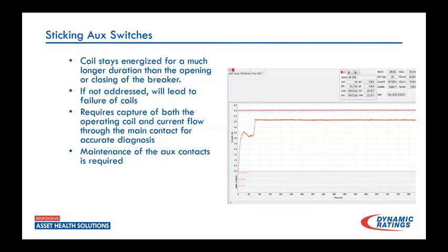And again, with more operations, you'll see this start to change. It may get better apparently after you operate a few times, but if it's really something you have to go in and do some maintenance on this, because the coils are not designed for this sustained current for this amount of time. So as this breaker operates, within 10 or 12 operations, now you're going to be putting a trip coil in it. Again, that's after we have a breaker fail though.